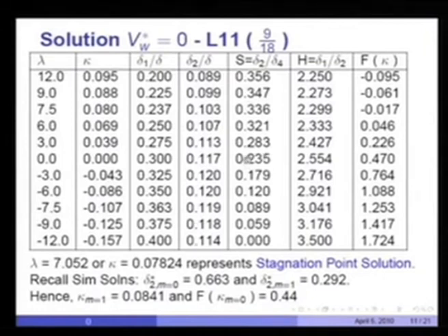Inverse is true for shear thickness. The shear thickness goes on increasing, whereas on the negative side, when there is suction, it goes on reducing, so much so that at minus 12 it reduces exactly to 0. The shape factor H, delta 1 by delta 2, is remarkably constant for highly accelerating flow on the acceleration side, but on the decelerating side it goes on increasing quite significantly. This is the right hand side with some values negative